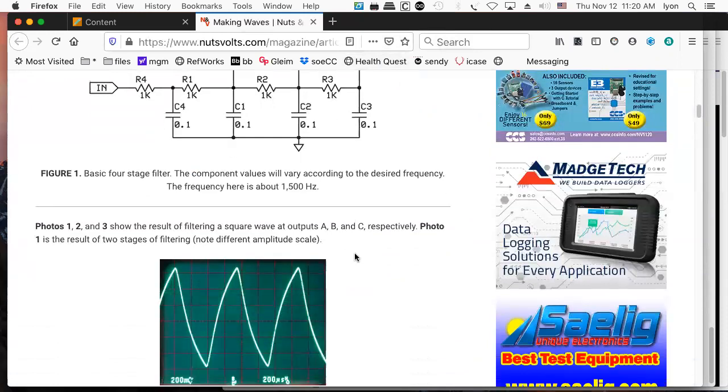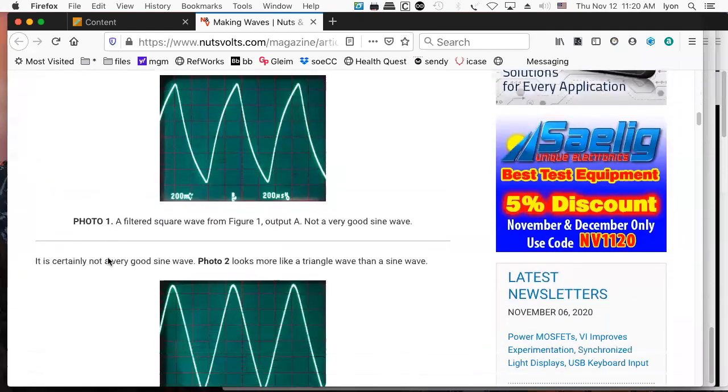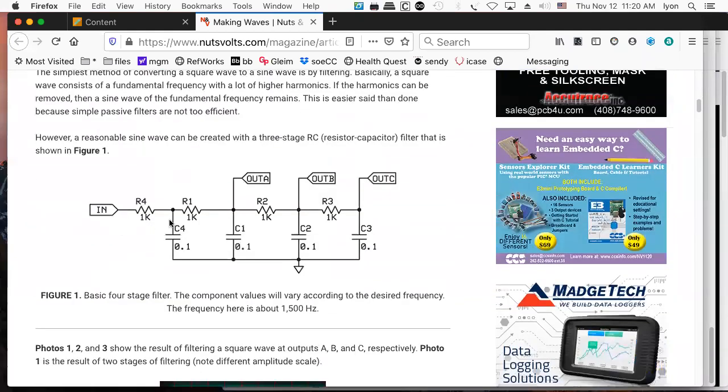It's not a particularly complicated lab unless you really want to understand what's going on with the multi-stage filter design. And then in that case, well, I can give you the intuitive idea that this is a low pass filter, but it has a cutoff, and this is another low pass filter, and it has a roll off, which is going to start at the same place as the prior one, but it'll continue to emphasize it. And each one of these represents another attempt to take out some of the high frequency signals.